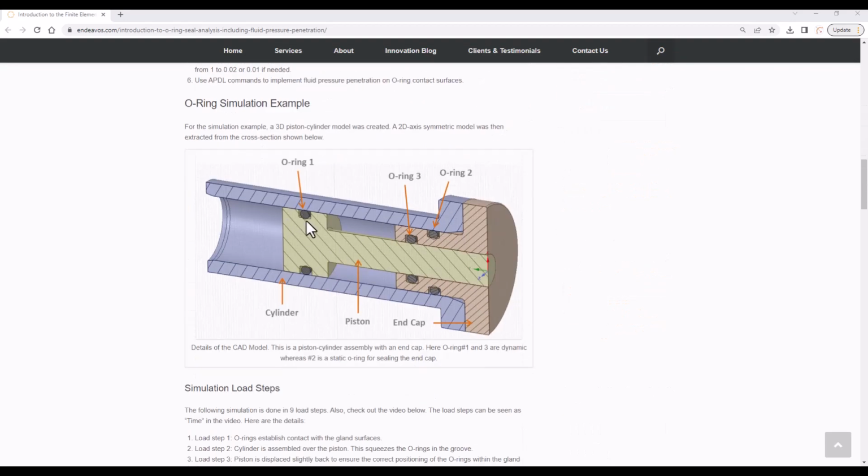So here, usually if we are going to put any seal in the assembly state, that is automatically going to be subjected to some type of pre-stress condition. That pre-stress condition is like, usually on the periphery of this seal, there will be some normal force that is already applied. On top of that, because this seal is designed to avoid any type of fuel leakage, if any fluid is present inside the system, that fluid is again going to cause some type of pressure loading over this seal. So it means that there are two types of loading. One is due to the pre-stress, another is that the fluid pressure will also be there.